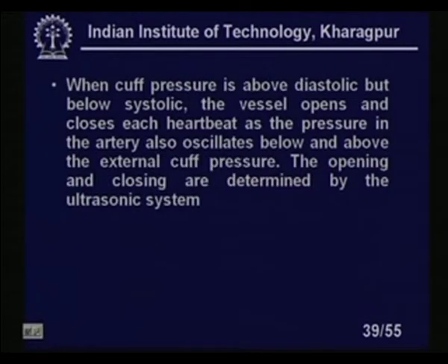When cuff pressure is above the diastolic, but below systolic, the vessel opens and closes each heartbeat as the pressure in the artery also oscillates below and above the external cuff pressure. This opening and closing are determined by the ultrasonic system that I show. That means two different waves, and during opening I will get a signal like this one.